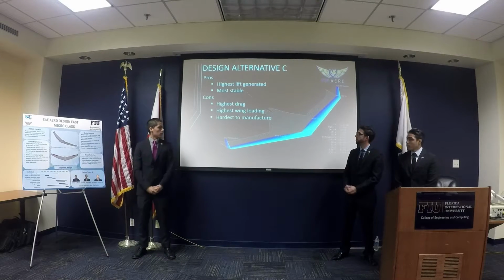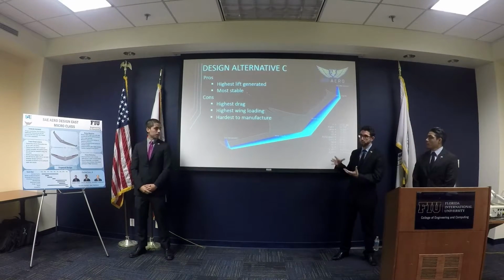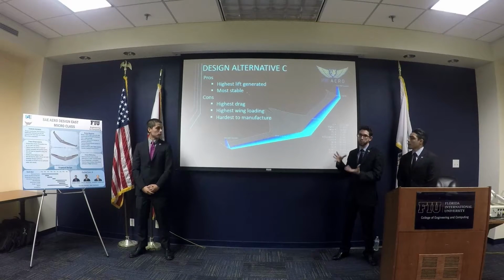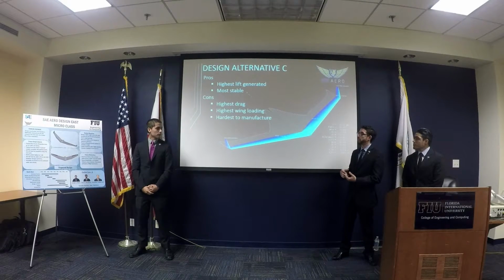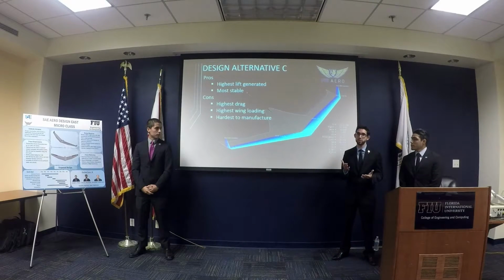I'm not sure. Right, so in our case, this is our final design. We didn't just come up with this. We iterated a lot. It was initially a pure reflex airfoil to make sure that the drag was appropriate, because what you're talking about is basically having a counter lift in the opposite direction of what you normally want to counter that pitching moment.